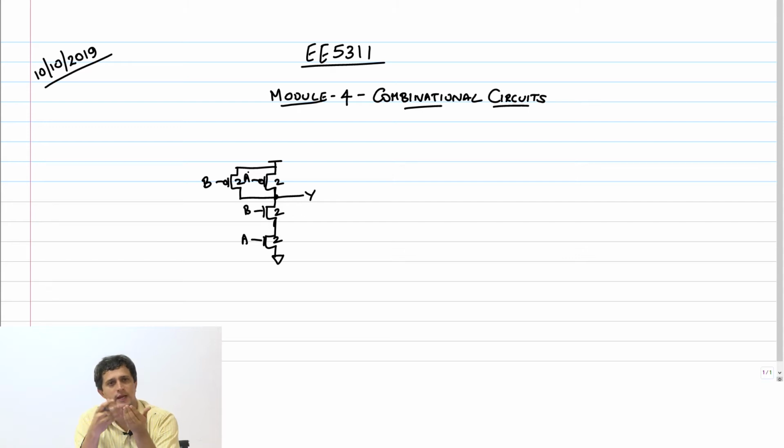I can swap these two and still not change the logic of the circuit, right? I can't do this, of course, with A plus BC. I cannot just swap any of the inputs. Logic will change, right? Now, when the logic is identical, which input should I feed to which transistor? Is there a choice? Are they equivalent or not? And this question also comes in this AB plus BC plus CA circuit that you did, right? You have 3 transistors and you have to pick the transistors and assign the inputs appropriately. Okay. So let's look at this and let's look at the pull down part.